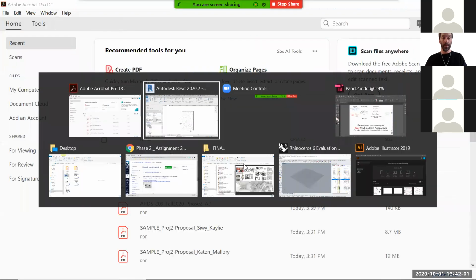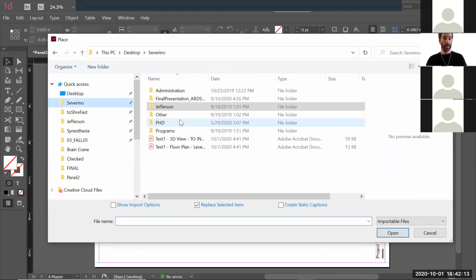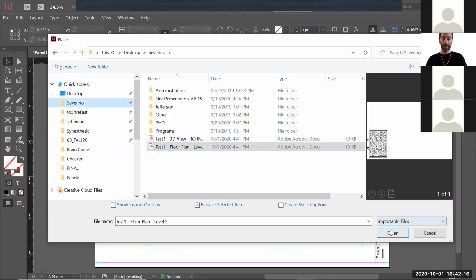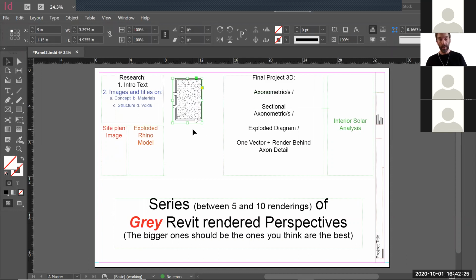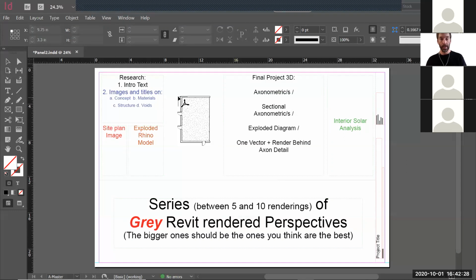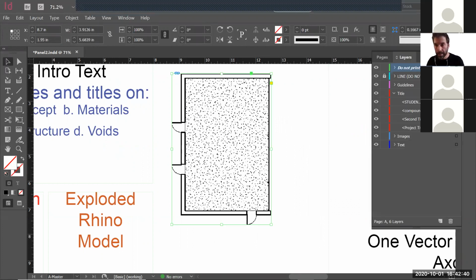I have two PDFs. I go to InDesign and I have the plans. I get rid of this, for example, and I say place. Plan. If you place in InDesign and you do this, meaning dragging around, you just ruin the scale problem. So you have to only click once. This clicking once is exactly 1/8 of an inch equals 1 foot. So I do a, now another thing is this probably an improper layer, so do not print, make it, take it into the images or drawings.